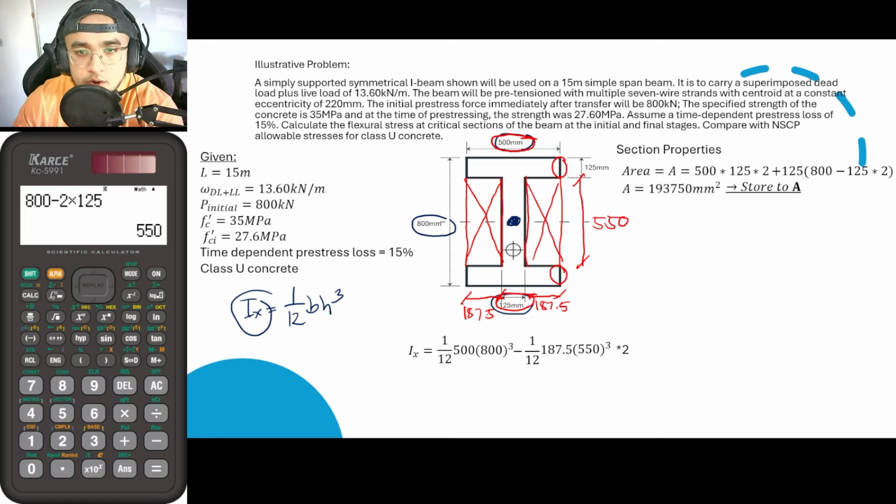So next question, do I still need a transfer formula here? We do not need to transfer any longer because their centroids also coincided with the centroid of this section. If you want to make use of the transfer formula, it would be up to you, but still, the value for d in Ad squared would be 0, so it would just simply cancel out.